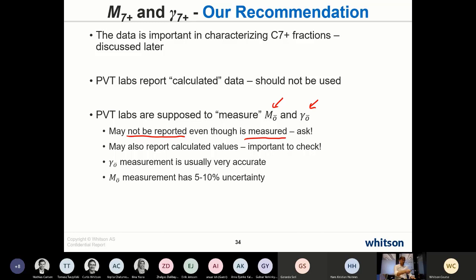There was a question here from Gulnar that this is on the stabilized oil. So that's a very important point, because the measurement of molecular weight and the density here is done and only relevant on stock tank oils. So for the two reports that we have, it is a flashed oil for the black oil case.